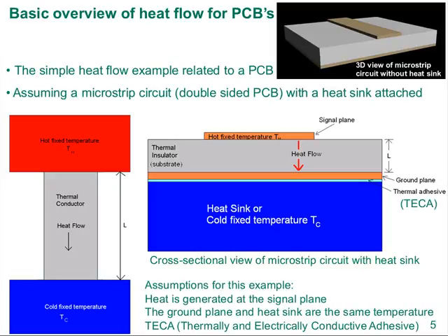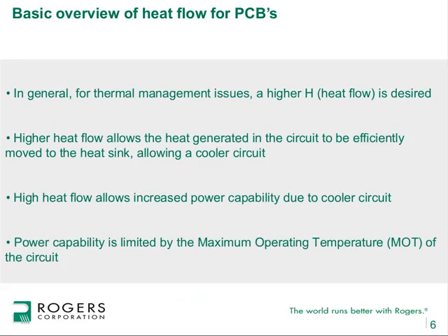In reality, there's more to the story, but for a simple model, this is okay. The ground plane is assumed to have the same temperature as the heat sink, so it's the cold reservoir. The circuit ground plane and the signal plane is the hot reservoir. What connects these together in a thermal sense is the substrate. So the substrate is acting as the thermal conductor, but it's really not that good for thermal conductivity. If you look at the numbers, which we will, the thermal conductivity of most substrates used in the printed circuit board industry is not that great. So it's acting as a thermal conductor, but in reality, it's more of a thermal insulator, and that's some of the problem.